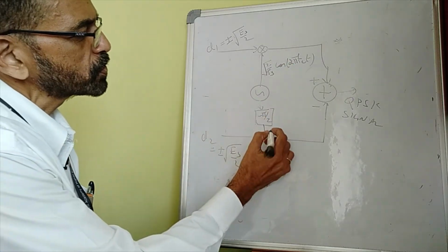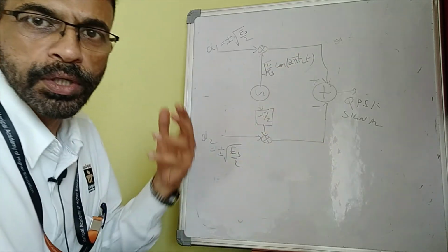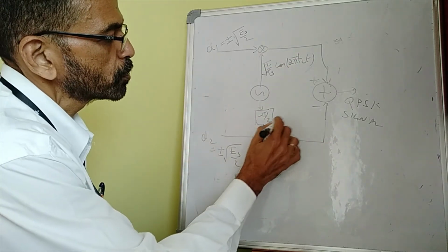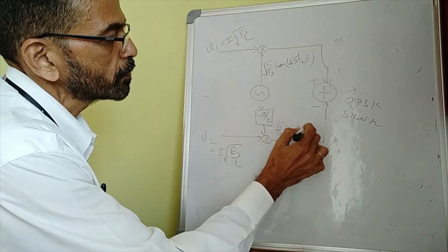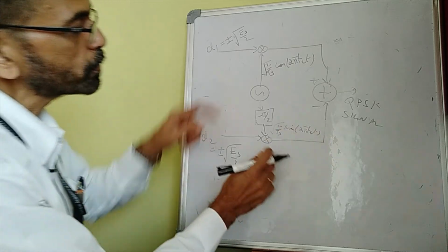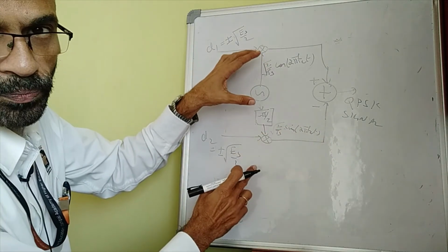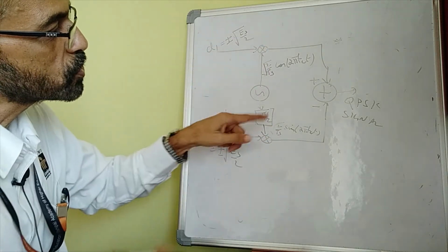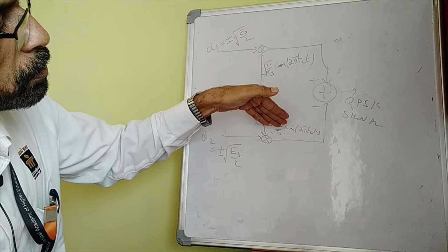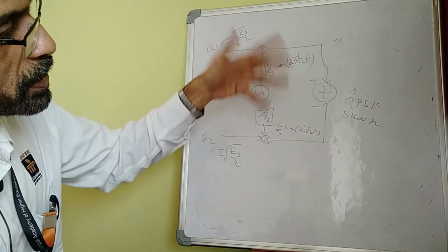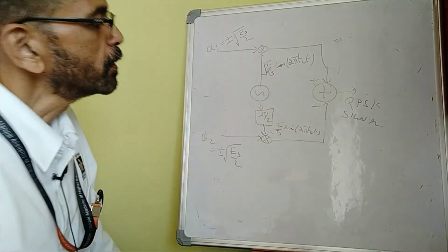And after the phase shift here, you will get cos(2πfct minus π/2), that will give you sine 2πfct, so root of 2 by Ts sine 2πfct. Between these two, the relative phase shift is minus π/2, the phase difference. So this is advanced in phase by π/2 with respect to the signal that you have here. That's what it means, and it is generated from the same oscillator.